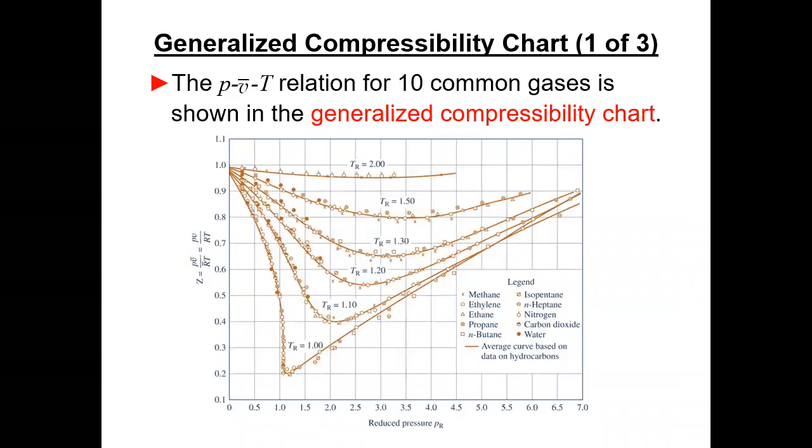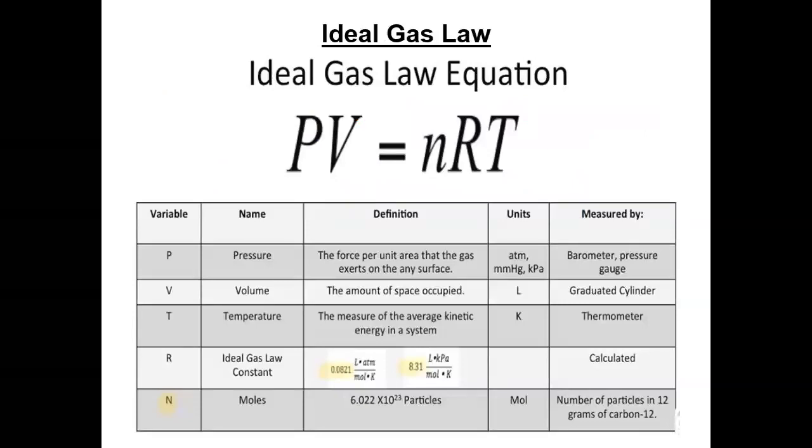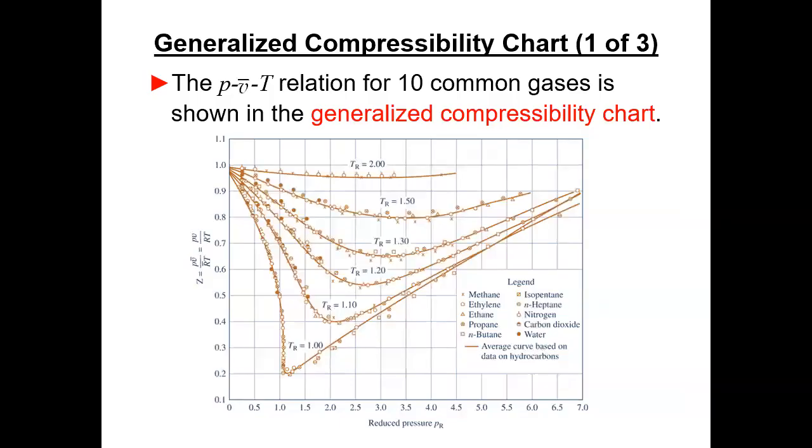Is this the first time y'all have ever seen a chart like this? I kind of think so. Yeah, I don't think they do this in chemistry. Well, it turns out that if you really look at a wide range of pressures and some pretty high temperatures, this relationship doesn't always work real well. And so this Z, this compressibility factor, is a fudge factor that is basically measured and correlated, that you pull off a chart like this and you include that.